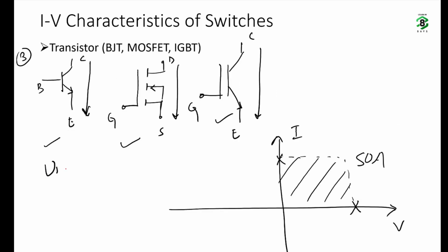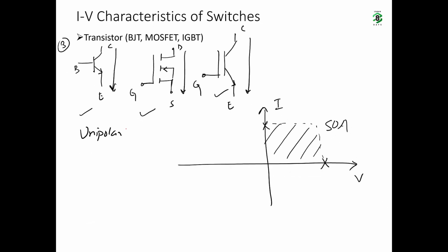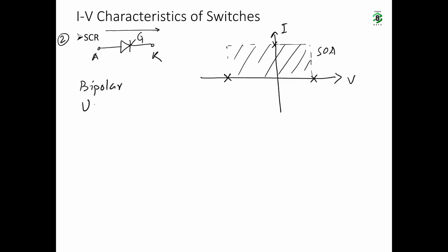Okay, so previously, transistors: unipolar, unidirectional, fully controlled switch. SCR: bipolar, unidirectional, semi-controlled switch.